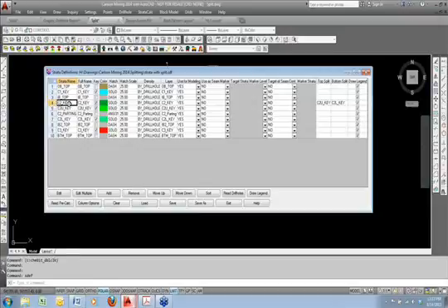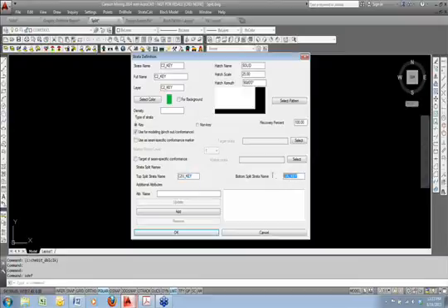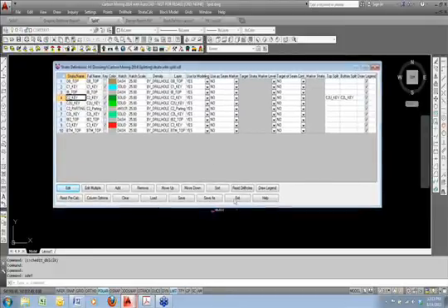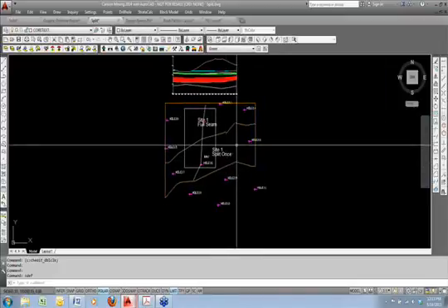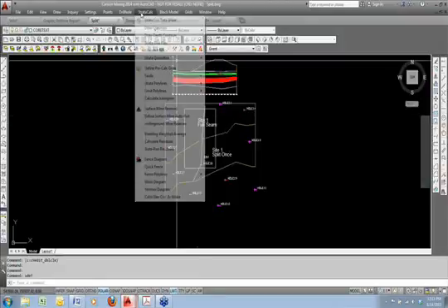The typical definition is the C2 parent is defined to split into the C2 upper and C2 lower. Now that's not new, that's always been there. That way it correlates the roof and floor of the C2 parent to split into these smaller children's seams. What's new though is we would model this the same as always where it's split everywhere. But then when you run surface reserves or you do any other model analysis, and even fence diagram, it automatically joins them back together based on the parting thickness.